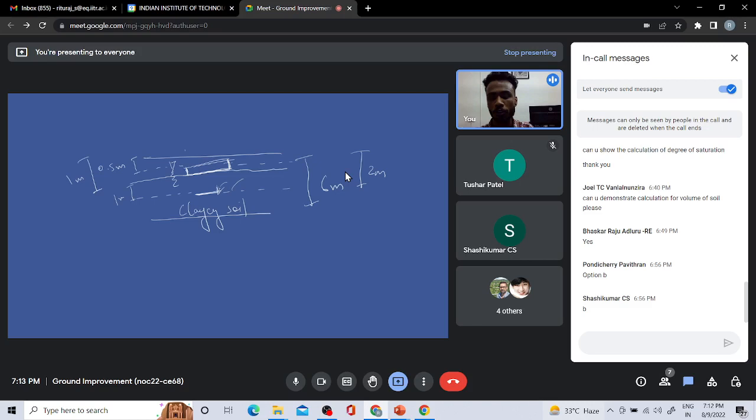So I guess if the water table is present, engineers generally avoid this excavation and replacement method. If you have gone through the slides, they mention that if the water table is present at that depth, they ignore replacing the soil. They either use some pumping or drainage methods to first drain out the water.